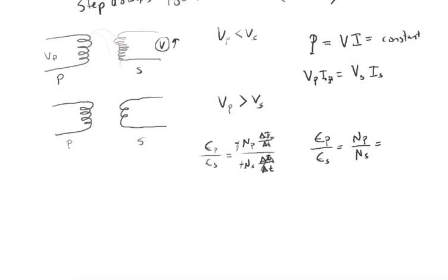I mean, just divide it over. Vp over Vs, which is this, is going to be Is over Ip, right? That's just right from that equation right there, right? Because voltages are EMFs. So divide the secondary, so you have primary over secondary in voltages, and then this would divide over, you have secondary over primary here. And so this will be our result for what transformers can do.